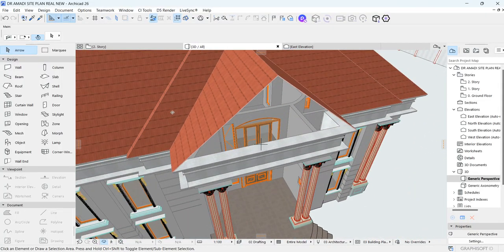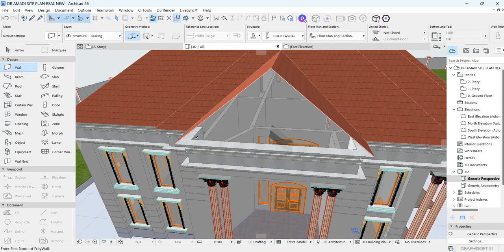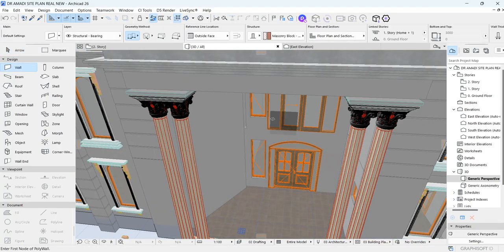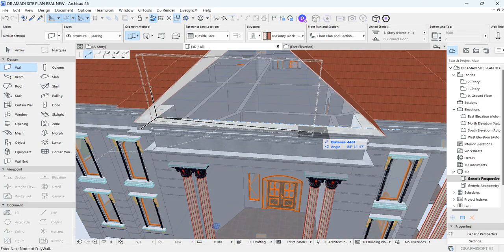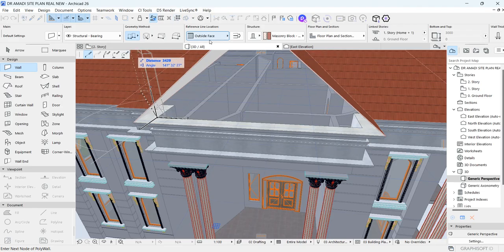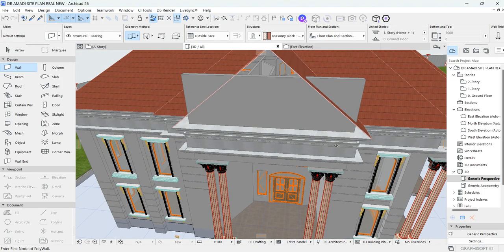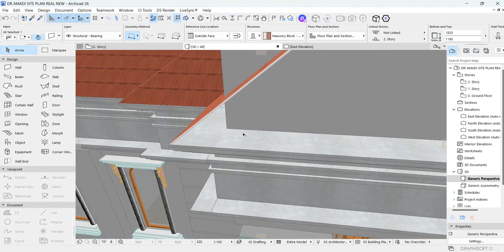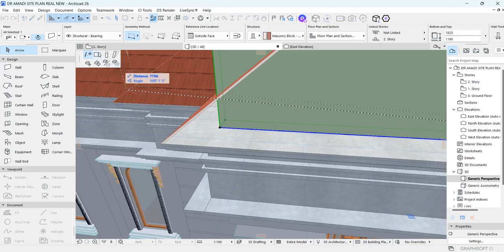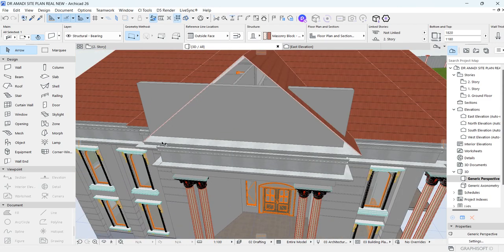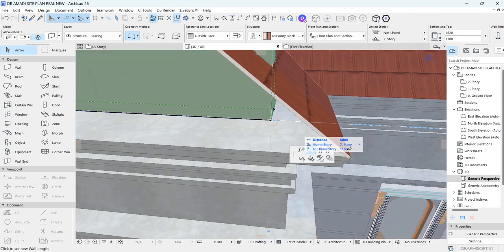And then what I will easily do is draw a wall here. Okay, from this point. Okay, no. I have to pick. Let me pick any of this wall. And then, okay, let me change the face. Okay, no, I don't want to crop. I will do that myself. So I will just stretch it to this edge, and to this edge.